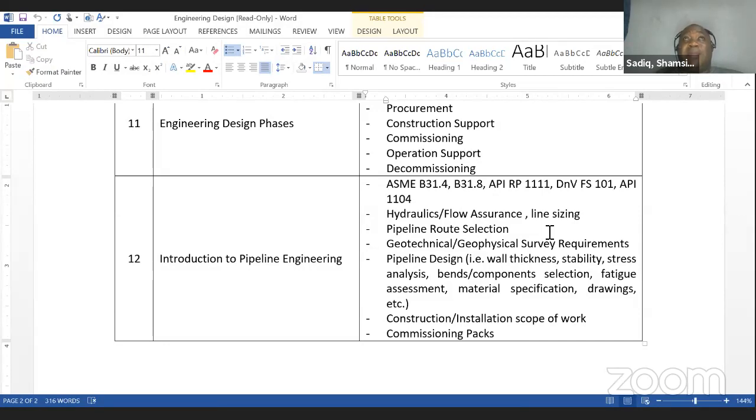When we talk about stability, we're talking about purely offshore, where a pipeline has to sit on the bottom of water all through its service life. You want a stable pipeline, one that is not affected by movement of water, because it can break the pipeline if it continues to move back and forth. Not rigid in the sense, but stable and staying at a single position. If it's going to move, maybe a very small movement in 1 year, 2 years.